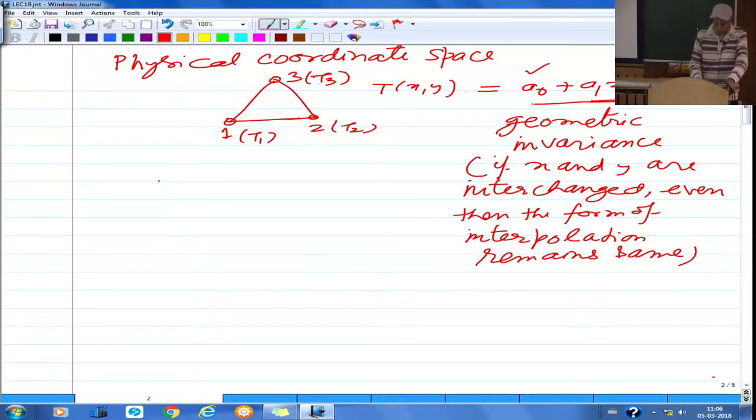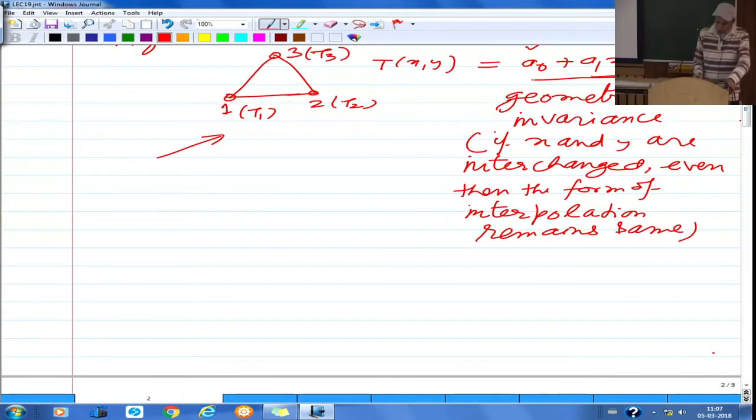So this is the simplest shape you can think of using for discretization of the complete domain. Then the next level of approximation you can have: rather than 3-noded, you can introduce the mid-side nodes. So like we talked of linear truss element and quadratic truss element with 3 nodes, here if you have the mid-side nodes also. So these are, let's say, corner nodes, local nodes 1, 2, 3, and then this is 4, 5 and 6.